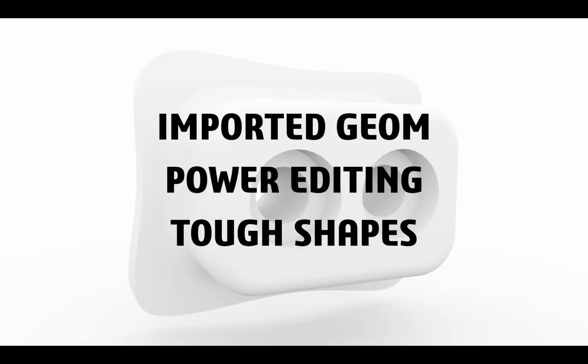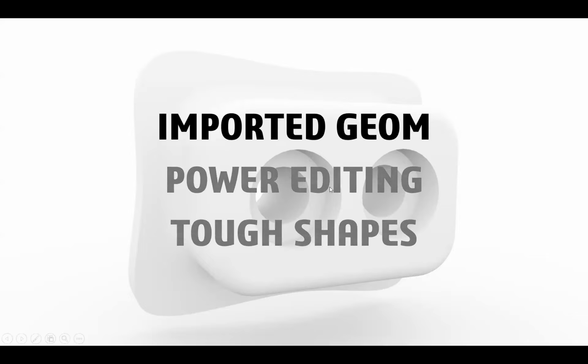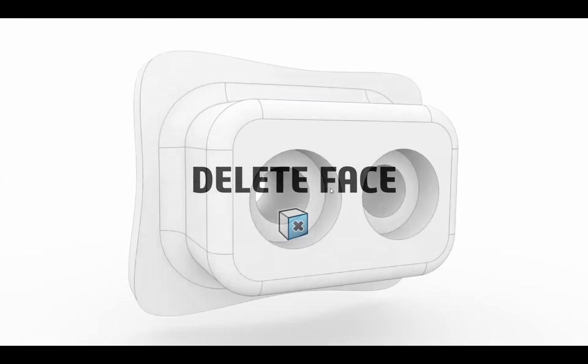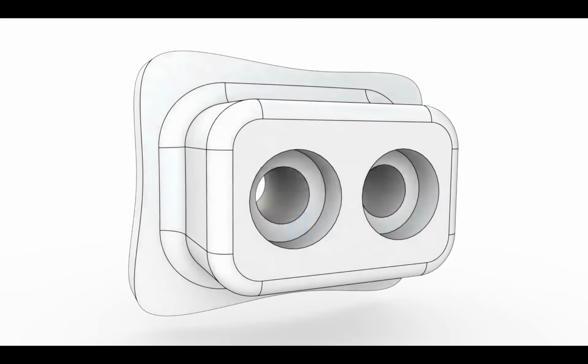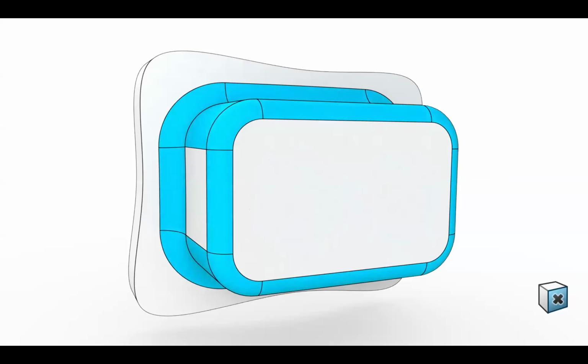Tough shapes is the obvious one. But for example, I'm going to show you a couple of these. Like delete face is probably my favorite, just a handy, quick surfacing tool. Maybe a bunch of you have already used this, so maybe this is kind of the duh example. You import something, if you want to recreate those holes, you just use delete face and it's got a delete and patch option and they're gone. Now you can recreate them the way you want.